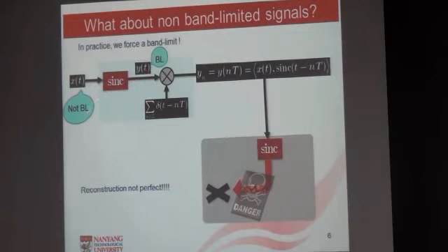But you say, well, let's take a sinc that has a very, very large bandwidth, so that we can have an approximation which is as close to x of t as possible. Now the thing is, if you filter a signal with a sinc that has a very, very large bandwidth, so that these two are approximately equal, when you sample it, you have to sample at twice the maximum frequency, right? So that means you have to take a lot of samples.